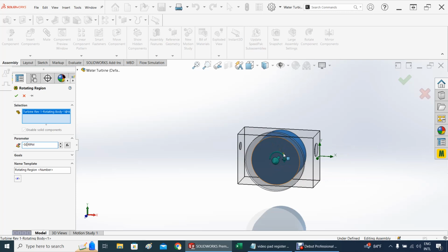Now if that torque for any reason became positive, it means that this is turning faster than is allowed because of water flow. You see, for example, if I put negative 1000 and there's a positive torque, it means that the water is resisting the RPM that I'm imposing on the system. It cannot turn that fast unless you impose energy. So as long as the torque is negative, it just means that you're extracting energy.